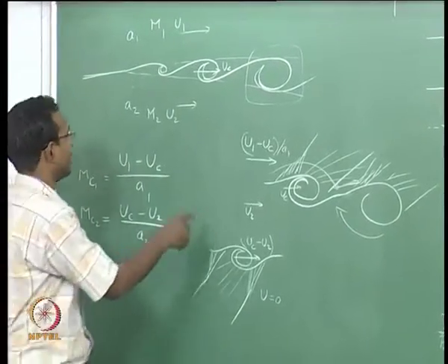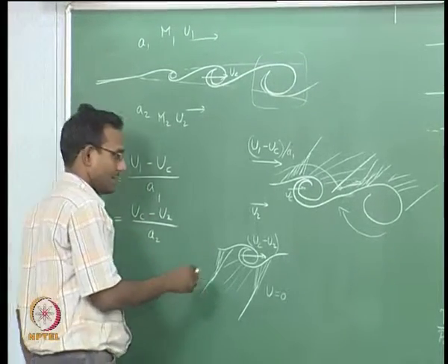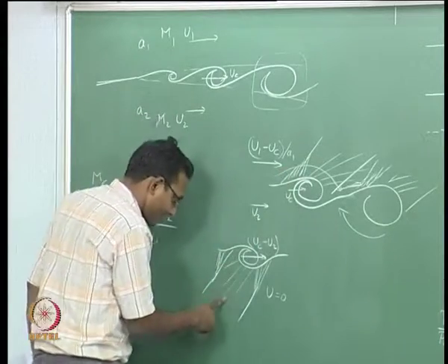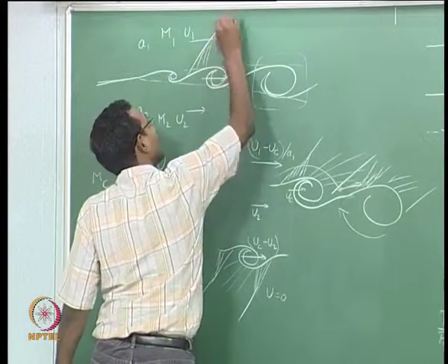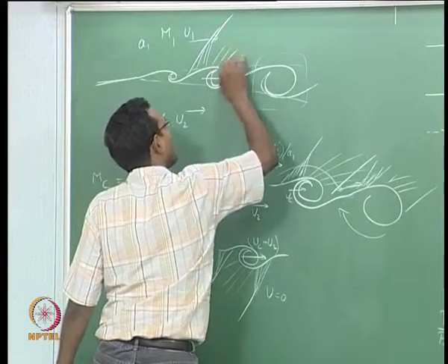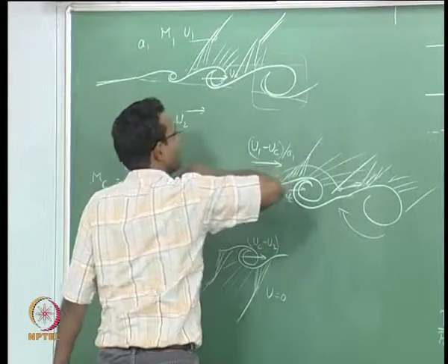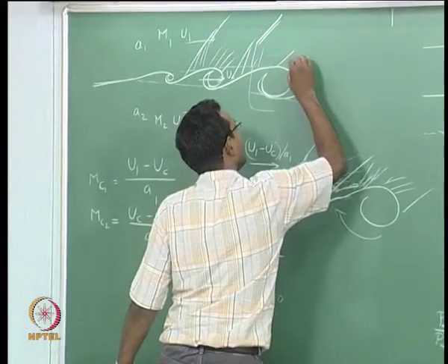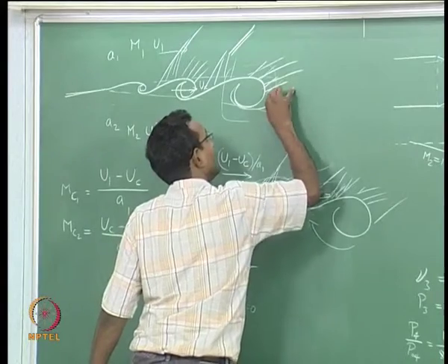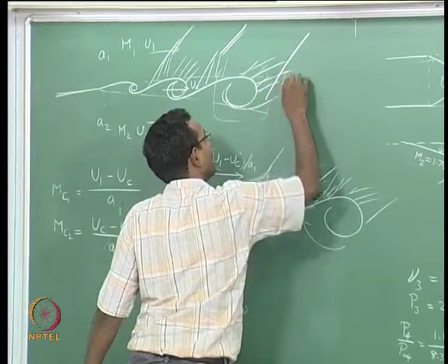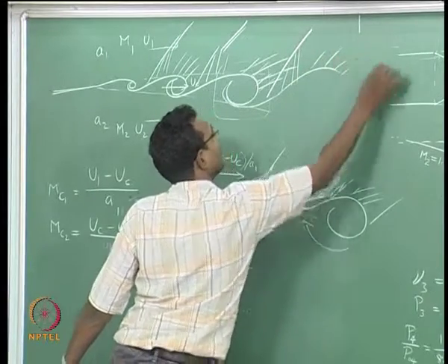So if I look at the whole thing with a high speed camera, we will start seeing this on the top and this on the bottom all together. I will draw all of them together: shock, expansion, shock. The whole thing together forms a shock, and then expansion again. The expansion will be at a higher angle like this, and then there will be a shock, and again a bunch of compression waves connecting with that, and the next expansion starting here.